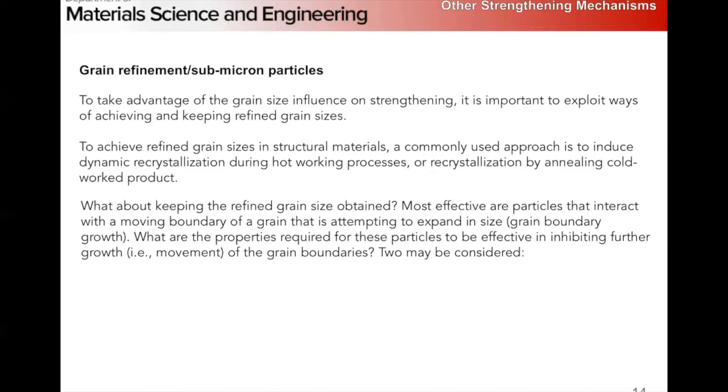right? So in recrystallization, we're talking about a balance between the stored energy in terms of the elevated dislocation content and the surface energy of the new grains, right? You're going to nucleate new grains to eliminate the stored energy, gobble up those dislocations, and leave behind a nice clean crystal lattice, right? But then now we've got a bunch of small grains. We have a lot of grain boundary energy, right? If we can grow those grains and eliminate grain boundary area, right, we can further reduce the energy of our system.